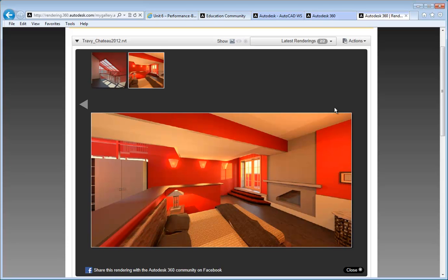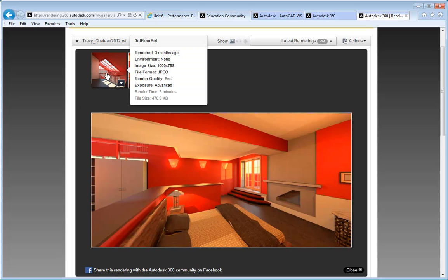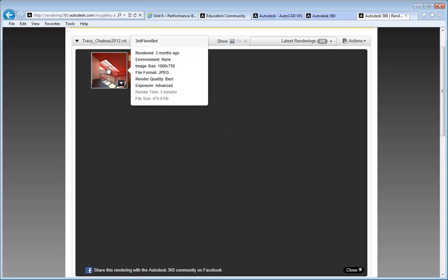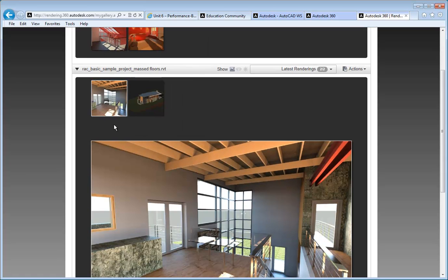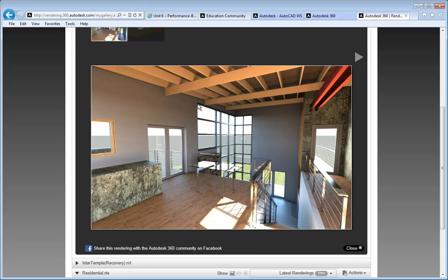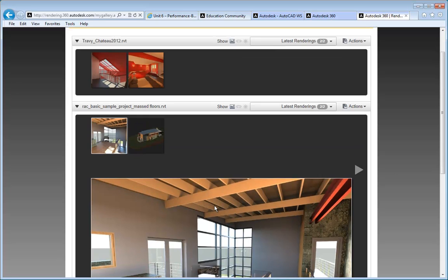Now what you can set up is multiple 3D views in your Revit application, and you can send them to the cloud, and in the background while it's doing its rendering, you can keep working on your project. And maybe if you're not working on your project, you're just going out or you have to leave, it'll send you an email notification letting you know that your render is complete and that you can now share it with whoever you're working with.